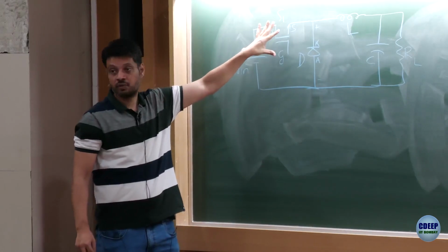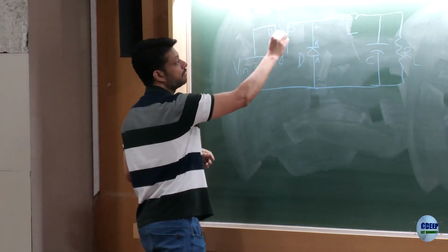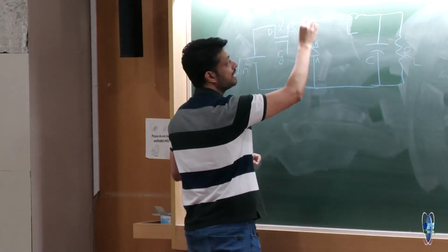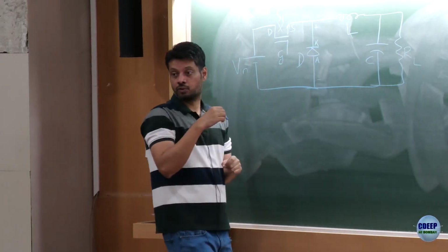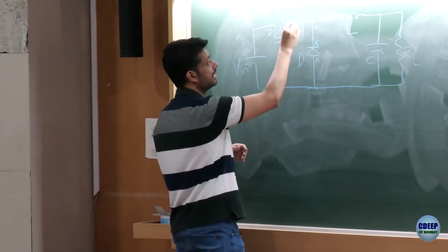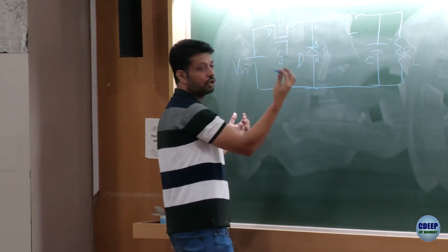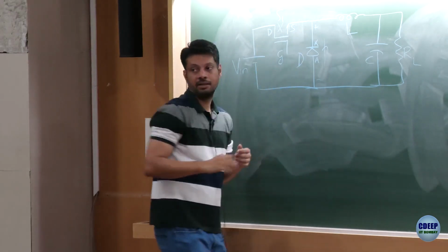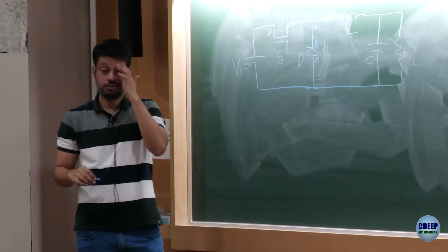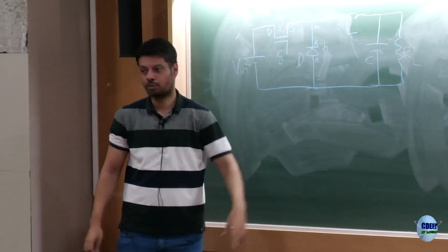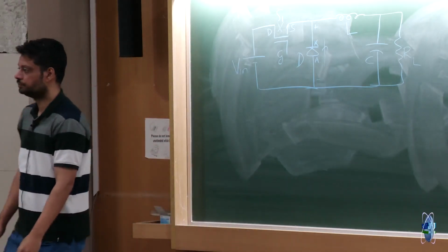Whenever the MOSFET is off, this channel is off, and the inductor still requires a path for the current to flow through, and this we have discussed in the previous lecture. It cannot flow through this channel because it is off, so it flows through this diode. So automatically when this turns off, this guy turns on. So this somehow meets our requirement of S1 and S2.